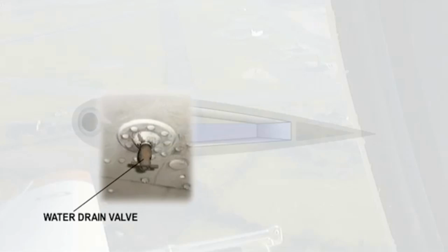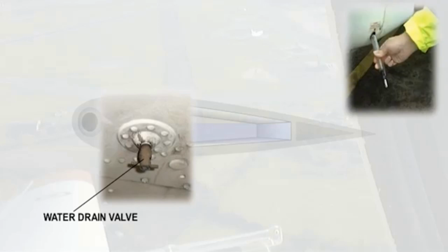Each fuel tank is equipped with a quick drain. This is located at the lowest part of the tank, sometimes within a sump which will collect any water as it settles. These wing tank quick drains should be used first to drain the sumps. Sufficient fuel should be allowed to flow to ensure removal of contaminants. This fuel should be collected in a suitable container, examined for contaminant, and then discarded.